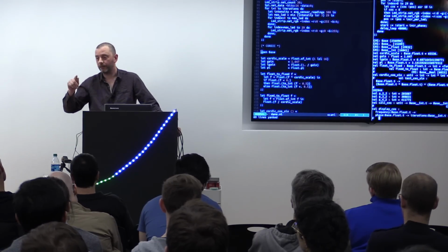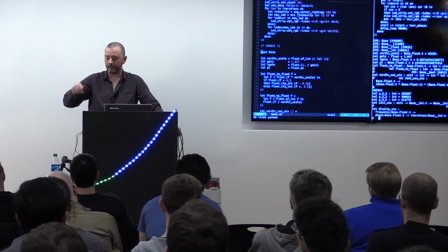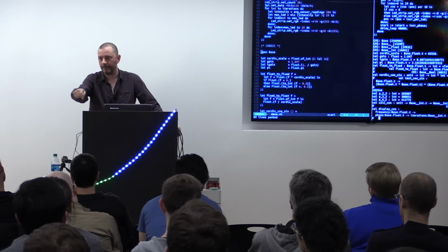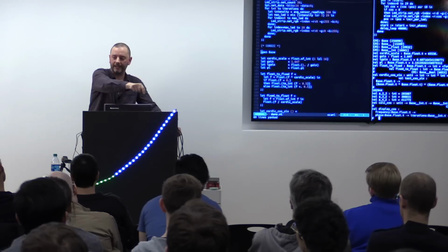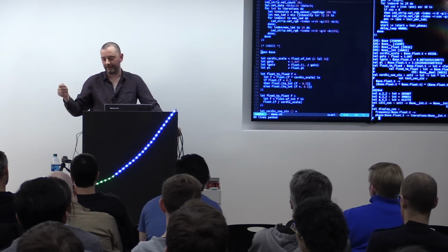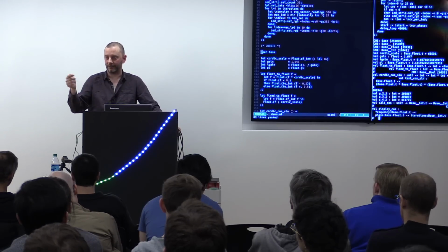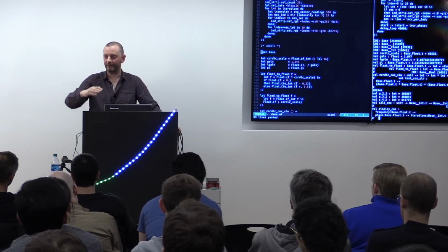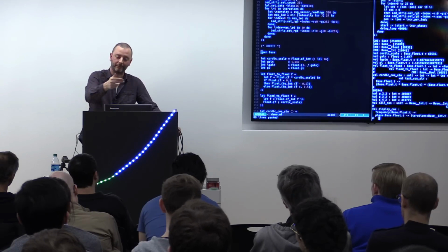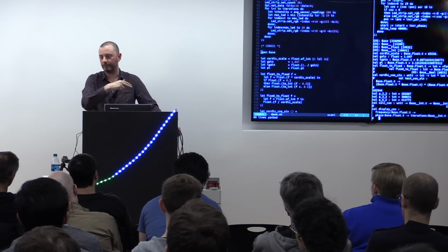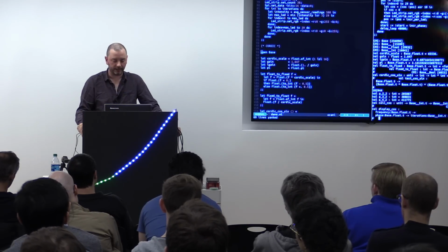It's got one bit that is used to drive the RGB values for all the LEDs across this. And so you have to send a pulse width modulated bit pattern to tell it when ones and zeros are, and you program the first one, put it into some sort of reset state where it holds its value, and then you're programming the next one, and so on. You just strobe across the strip doing that.